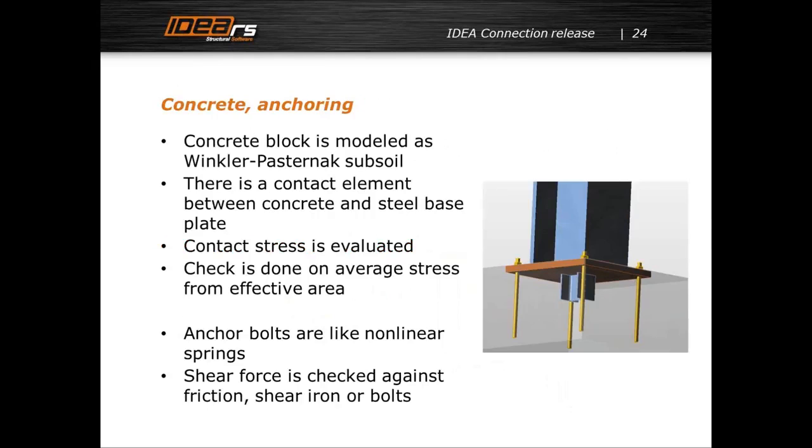This story is about this base plate. Again, a little bit of theory. There is concrete in the joint, and we decided to model the concrete like a Winkler-Pasternak subsoil, which is normally used for design of buildings. So if it works for buildings, why can it not work for connections? Only the stiffness of the material is different. It's not soil, it is concrete.